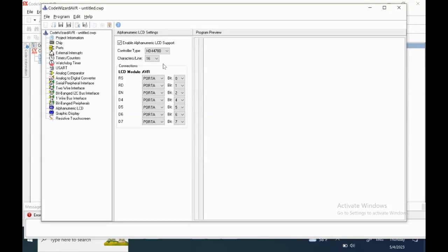our AVR ATmega16. Then here it's required to choose port A. Or, for example, if I want to interface the LCD with port B of our AVR, you see that I choose all of them as port B. And then it's not required in my coding to write the code related to configuring port B for interfacing with the LCD.